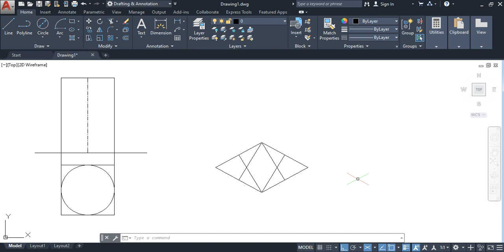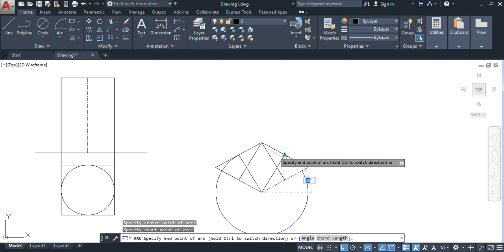And here we'll draw the arcs such that all arcs will represent the circle. So I'm telling the procedure for drawing the circle in the iso top plane. We have to draw an arc. For that, first of all, suppose we are drawing an arc here, this will be the center, and from here to here we have to draw the arc.